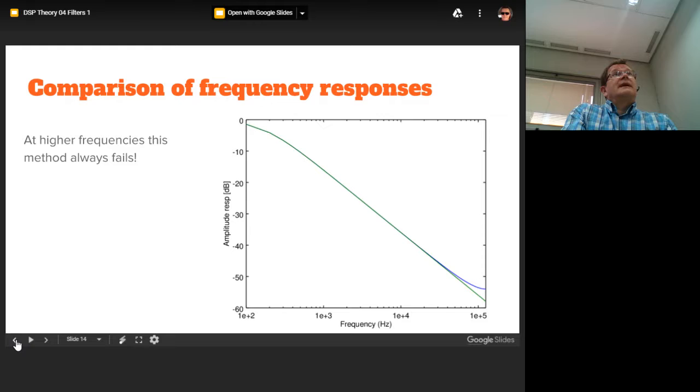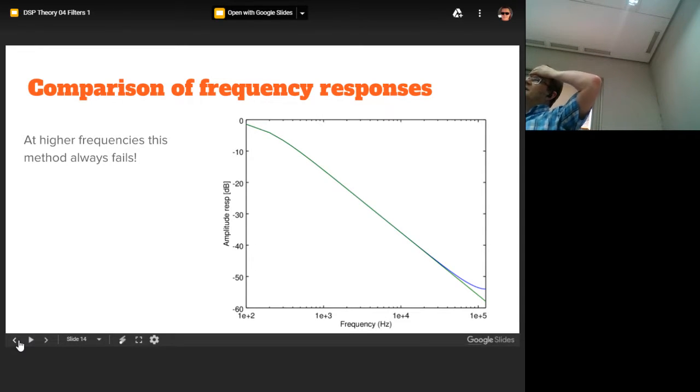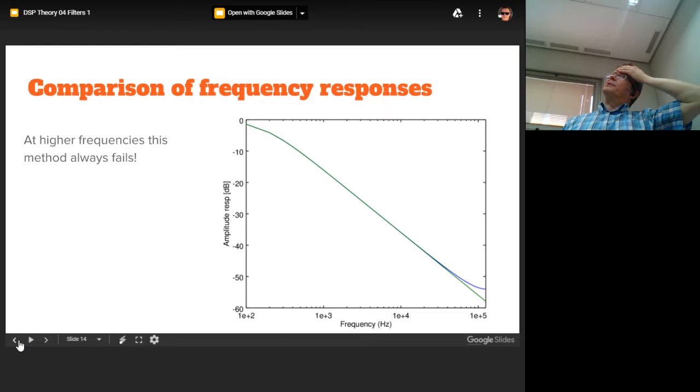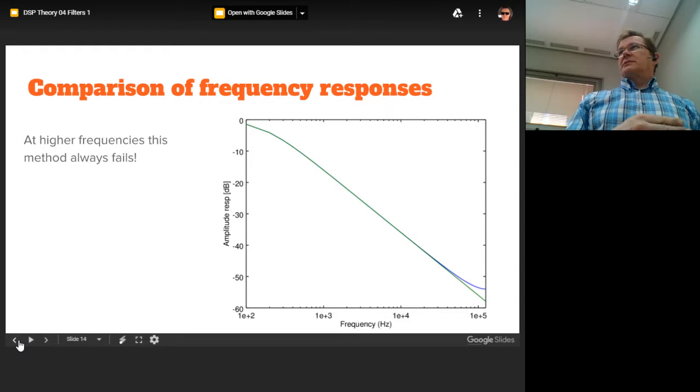Okay, and actually that one is a modeling of what happens if I didn't have any noise. Well, this is bound to fail because in real world you always have those high spectral components, and it means that if you are taking samples of that kind of system, the higher spectral components are showing up as the alias spectrum.